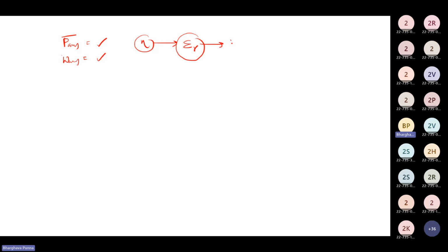For that, we use the velocity concept, omega by beta, and we have equated it to root of mu epsilon. So this one you should know. Then you have calculated the epsilon r value. Then you have calculated this eta. Then you have calculated the average power density. Then you have calculated the average power.